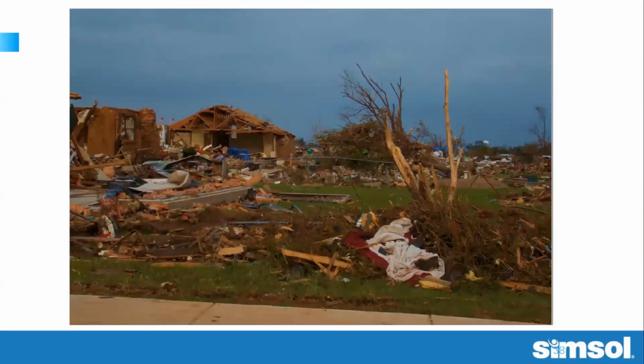Now, here's a good example of what we were talking about. The wind doesn't just affect one house. You see the house in the background to the left, the gable end's missing, most of the roof trusses are exposed, a vast majority of the roof decking is missing. Look at the house again to the left of that one, you can just see a corner of it. You can kind of make out a little window maybe there, and what used to be part of a fireplace going up, or chimney. There's no roof section on that. Notice the tree in the foreground, and notice the tree is kind of rotated, almost like somebody tried to unscrew it from the ground. This is very characteristic of not just wind damage, but tornadic wind damage.